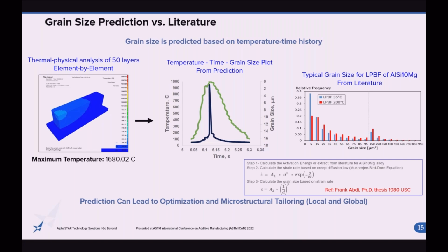webinars. As you can see, there's a fixed temperature at which the analysis is taken for those 50 layers of that initial level build. Grain size predictions for the material system are distributed over a fixed range in the physical measurement in the test literature, and ours is kind of spiking at a specific point. As you can see on the right side, it's showing the types of grain size from the literature. There's a kind of distribution there depending on the temperature.